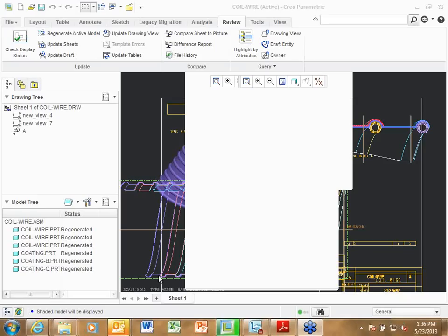The other thing that you can also do when you get into a table form, particularly with an assembly, and this is something that I worked through earlier this week, is if I have a family table with variations within that, I can bring in that family table and all those parameters and populate that dimension with a repeat region that sits within that table.